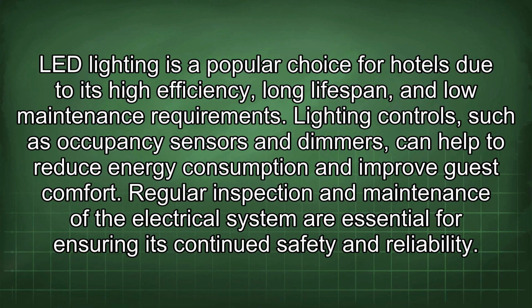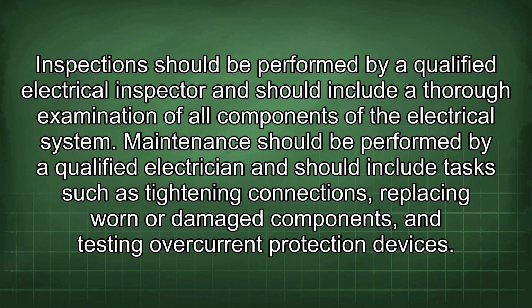Regular inspection and maintenance of the electrical system are essential for ensuring its continued safety and reliability. Inspections should be performed by a qualified electrical inspector and should include a thorough examination of all components of the electrical system. Maintenance should be performed by a qualified electrician and should include tasks such as tightening connections, replacing worn or damaged components, and testing overcurrent protection devices.